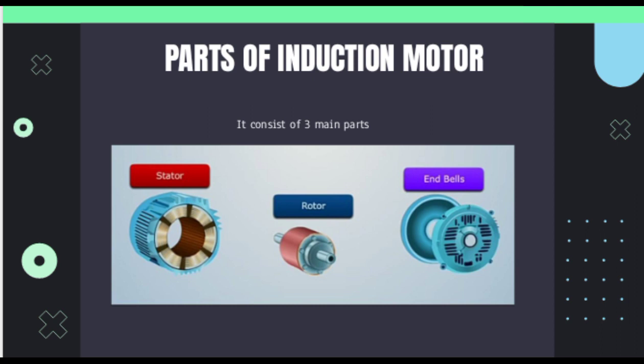The rotor is the central component of the motor and is attached to the shaft. The rotor, usually of copper or aluminum strips, attaches at each end to a circular attachment. This configuration is called squirrel cage rotor because of its appearance. The magnetic field generated by the stator induces a current in the rotor, which in turn creates its own magnetic field.